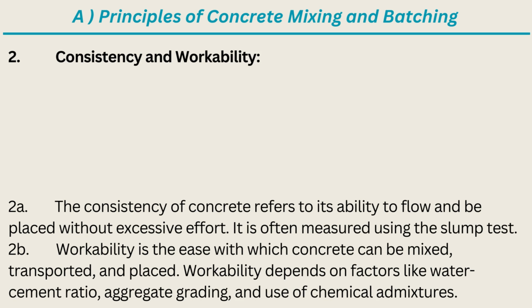2. Consistency and workability. 2a. The consistency of concrete refers to its ability to flow and be placed without excessive effort. It is often measured using the slump test. 2b. Workability is the ease with which concrete can be mixed, transported, and placed. Workability depends on factors like water-cement ratio, aggregate grading, and use of chemical admixtures.